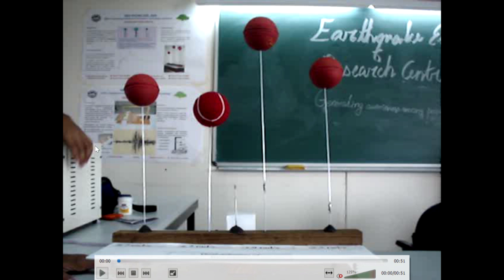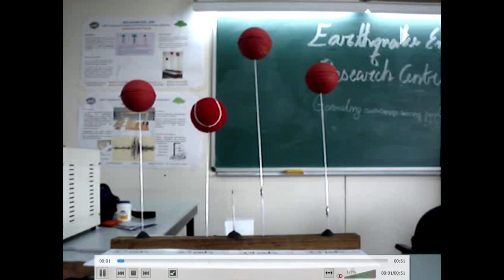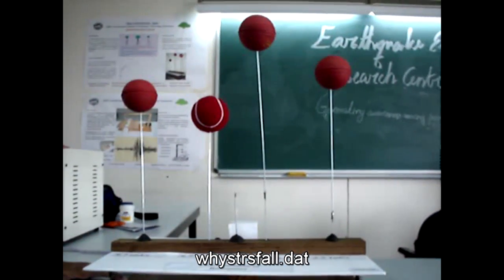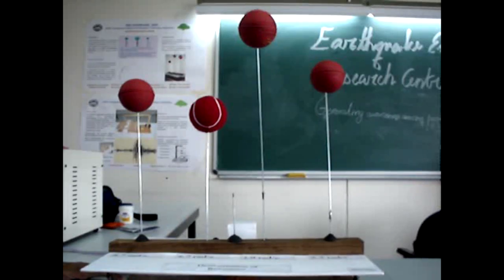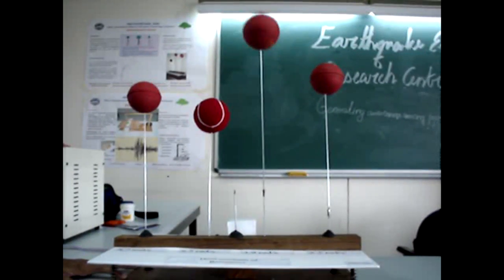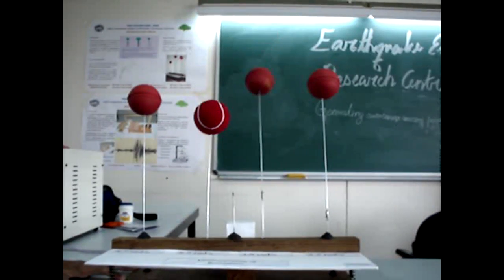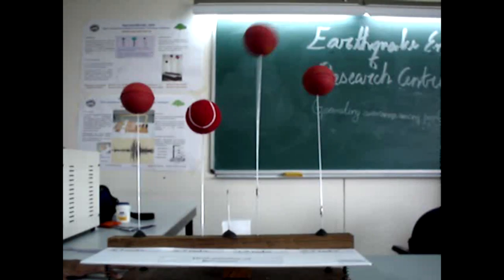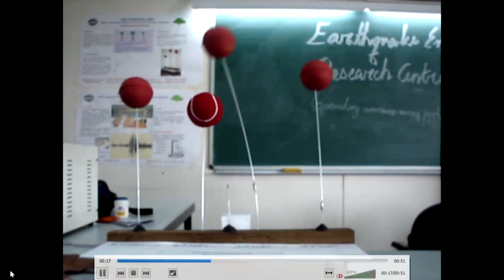Let us look at it. Now, as you can see, a slowly varying acceleration, that means a slowly varying force, is applied. Because of which that frequency is matching with the natural frequency of the tall building. That is why the tall building is vibrating violently, with severe motion and severe displacements.